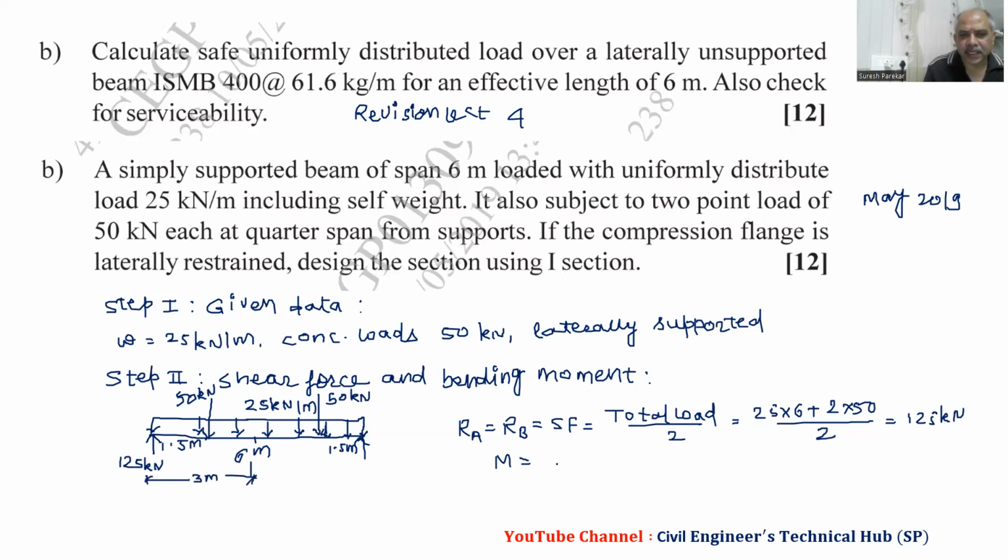Therefore M max is 125 into 3 minus 50 into 1.5 minus 25 into 3 square by 2, that is 125 into 3 minus 50 into 1.5 minus 25 into 4.5, it comes 187.5 kilonewton meter.